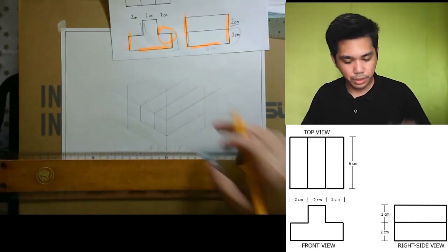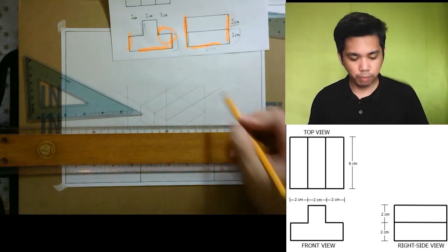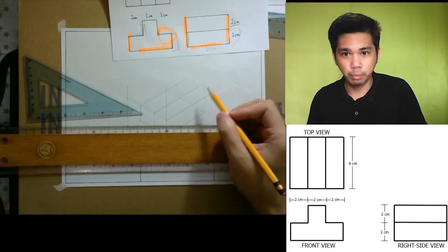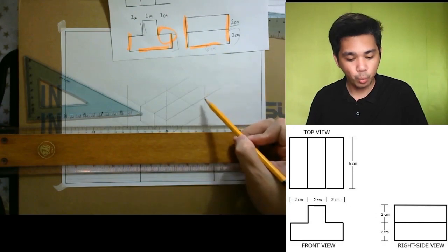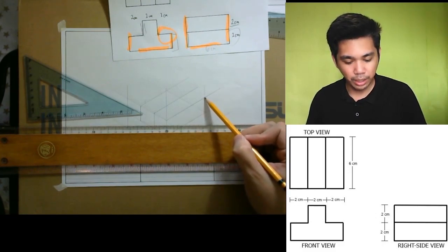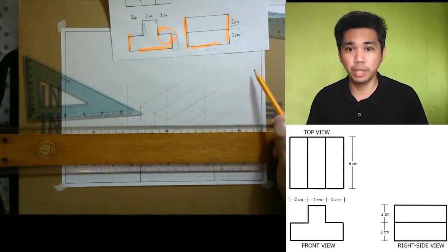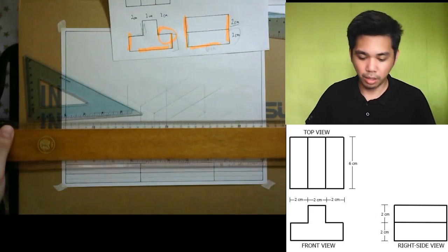Now let's look at the other side. There is a point here. You will also have to look where the line should go. So for example, this point, we have lots of options where to go by using 30-degree angles. We can go farther away, we can go inside, or we can go across. So in this case, since there is already a line here, and definitely we won't go outside of the object, so we have to put a line across the object.